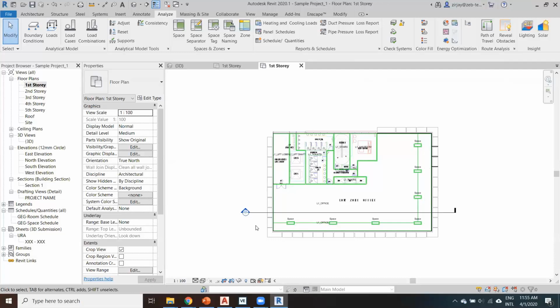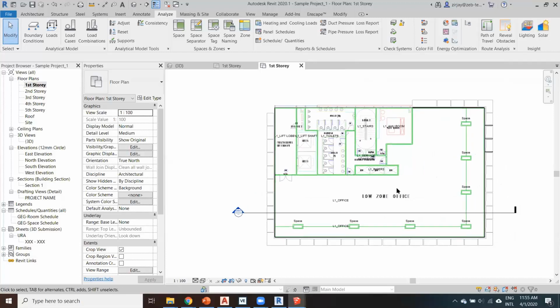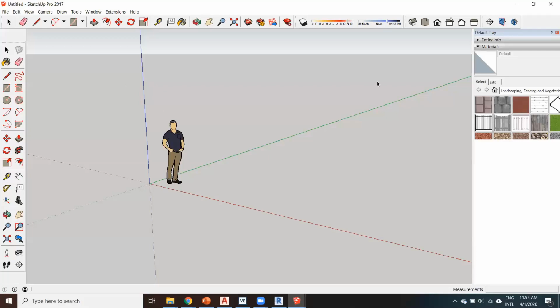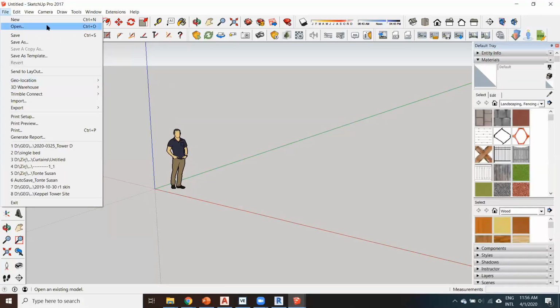And no way you can import the SketchUp as the energy model itself, because it just contains too much information. So definitely, if they only give you the SketchUp file, you'll have to export floor plans from it, and you have to create those floor plans individually for all those levels. So it's not going to be a productive process for you. So ask for the floor plans first.